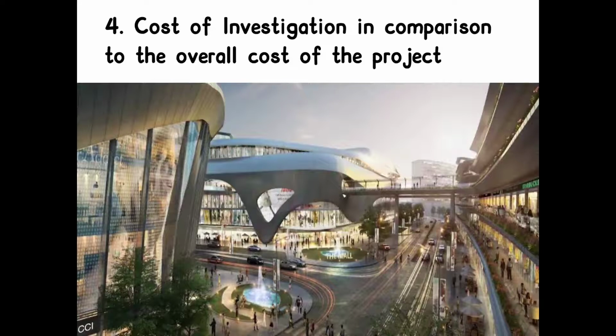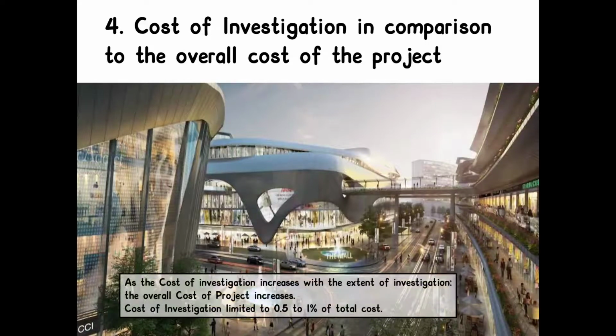Cost of investigation in comparison to the overall cost of project. When the extent of the investigation increases, the cost of investigation increases. This will increase the overall cost of the project. Therefore, the cost of investigation is limited to 0.5 to 1% of the total cost of the project.